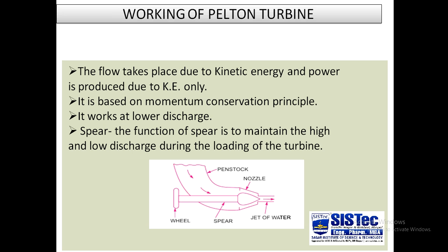Next, the portion to be discussed is the spear. So what is a spear? Generally it is a type of valve or a type of gear that is attached to the Pelton turbine. The function of the spear is to maintain the high and low discharge during the loading of the turbine.